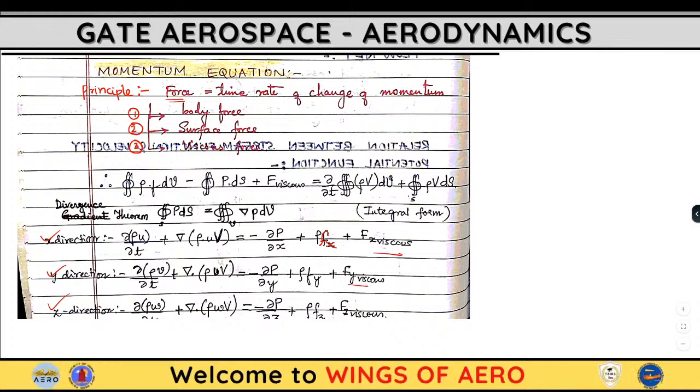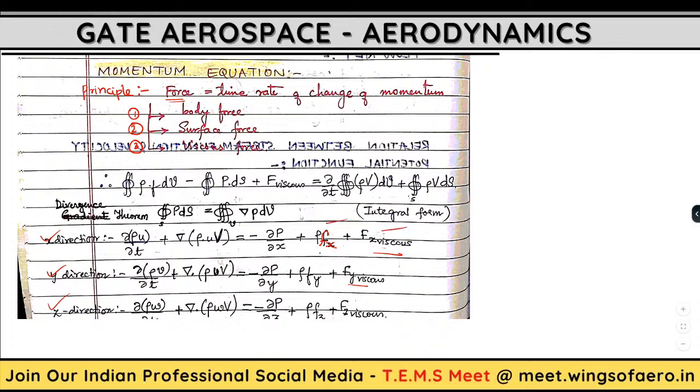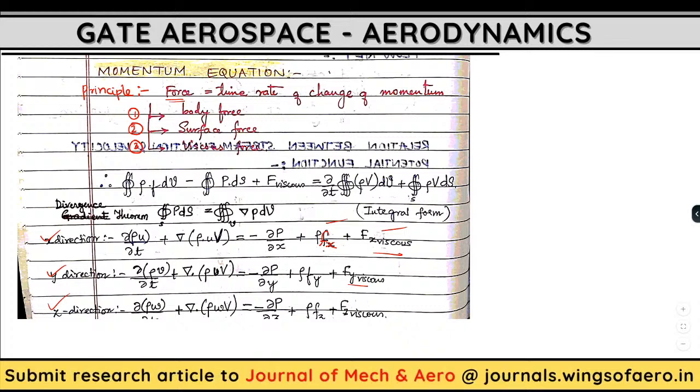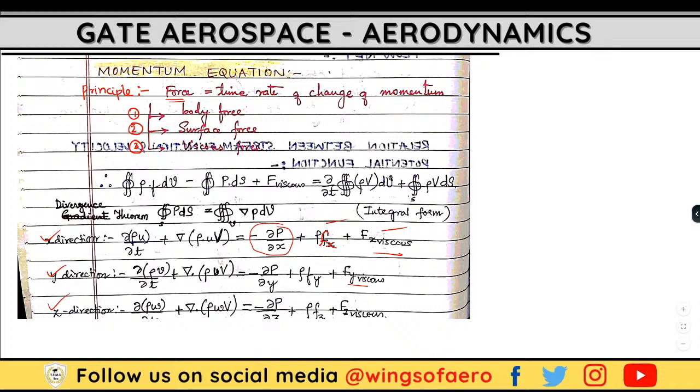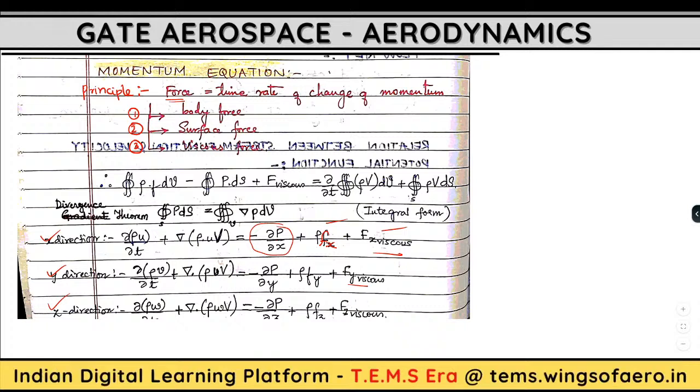And what happens with the surface force then? Which one is surface force? If this is a body force, viscous force, which one is the surface force? Surface force depends on the pressure acting on the particular system or a body. Okay? So this is the surface force. Alright. So they might ask you to identify the surface force and body force based on the equation again.